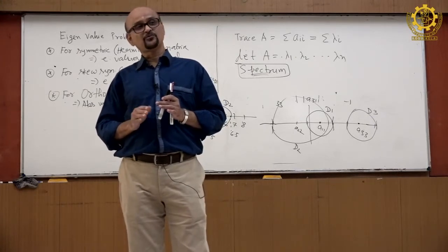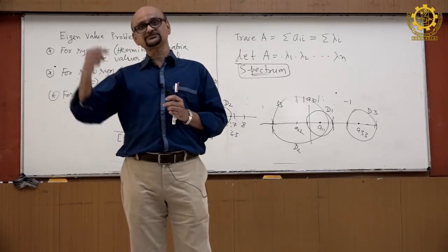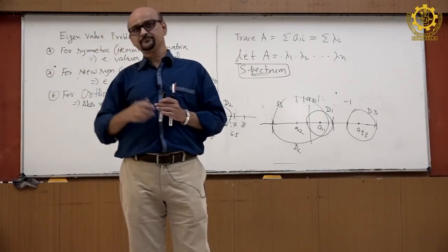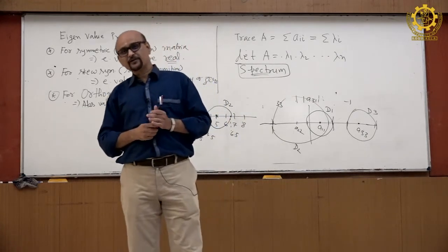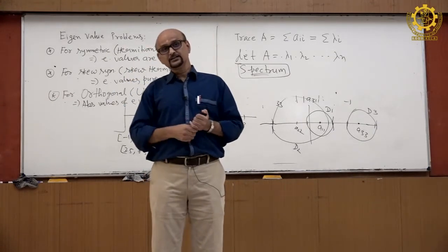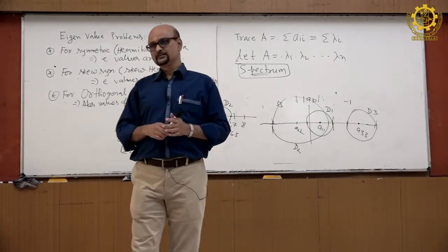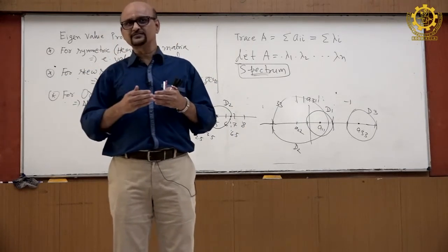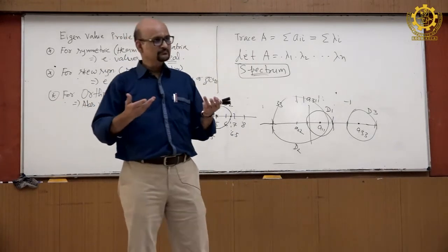That means when I have some force, some frequency will be there with that force. So I have to see that forced frequency with respect to the natural frequency of the system. Those lambdas whatever we are finding are natural frequencies, and those two, natural frequency and forced frequency, should not match. What will happen then? Resonance will occur. If resonance occurs, then it will fail.